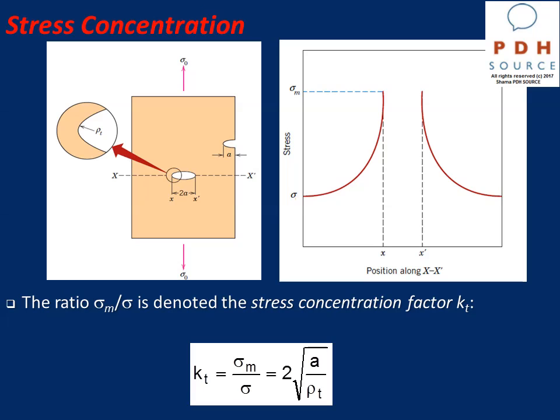Based upon this, we can conclude that the stress concentration factor Kt by itself will not provide the whole picture about the stresses in the vicinity of the notch. Consequently, we need to look for another parameter that is based on an analytical method different from the stress concentration approach.